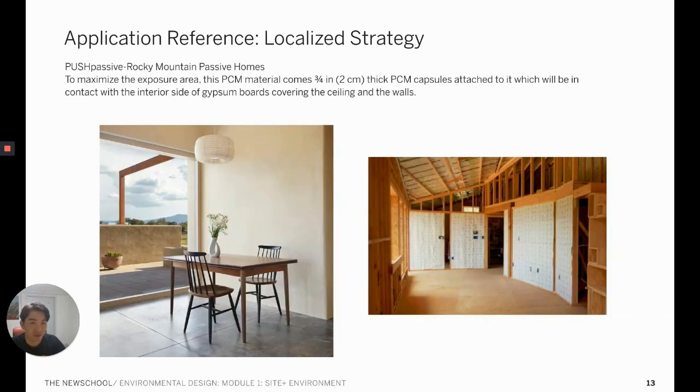On the other hand, for most smaller and residential applications, the PCM material is directly applied inside the interior partition, hidden behind the gypsum wall, providing heating and cooling capacity, and this is considered to be an efficient and passive building design strategy.